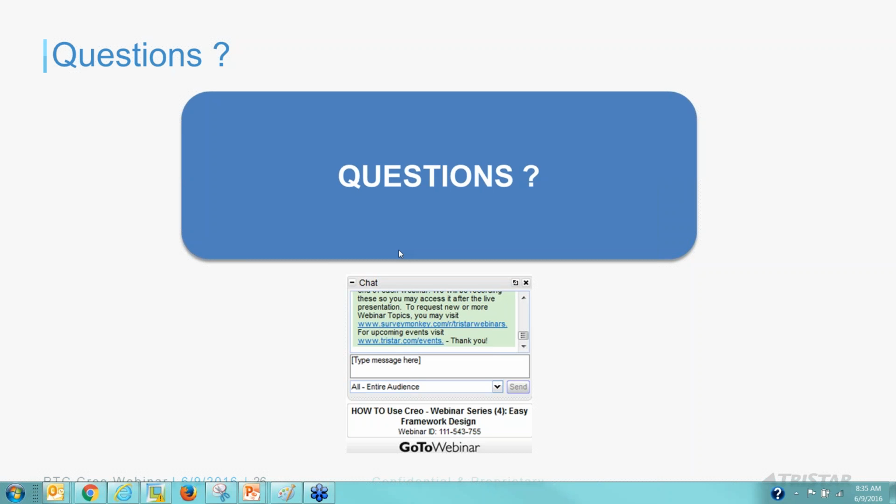What if I want to detail each individual member in the assembly drawing? Yes, in the assembly drawing, if you want to detail out each component, it's just the traditional method of activating that particular part. You have to activate that part, add it to the drawing, and then you can start creating dimensions individually for that part. I know the automation tool that I showed you created separate drawings for separate part files, but it can also be done in one assembly drawing.